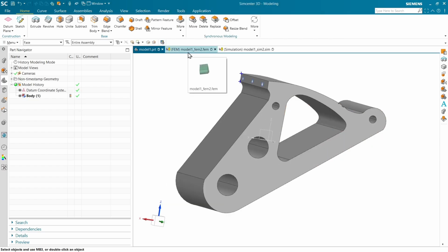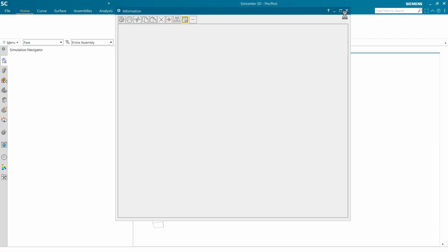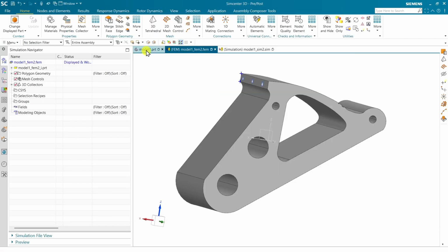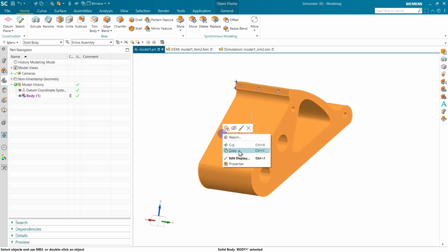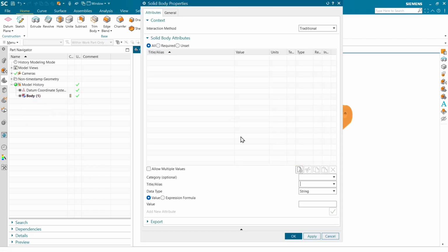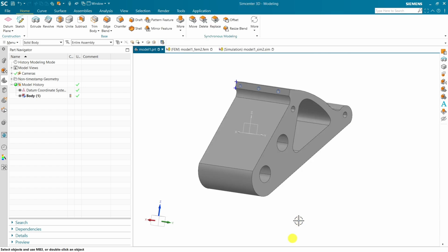Now what we have to do is go to the FEM. Let's select the body also, so that this will work for meshing too. In the face option, we'll change it to the solid body and choose this body, and right click properties, same way, body, and 3, and click OK.